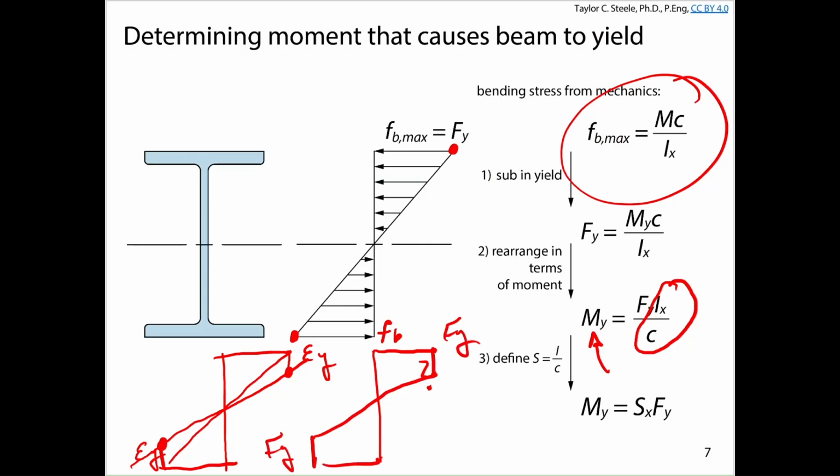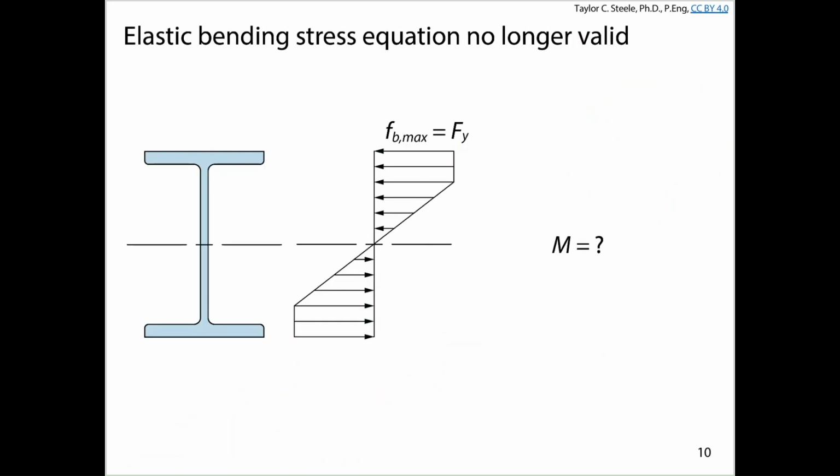And within the region where we are still within the elastic strain, we're still going to have a linear elastic stress in that cross section. Okay, so that might look something like this, right? We can say, okay, well, we'll exceed the yield strain at the extreme fiber, and we'll have the yield strain exceeded until we're maybe a distance something like this.